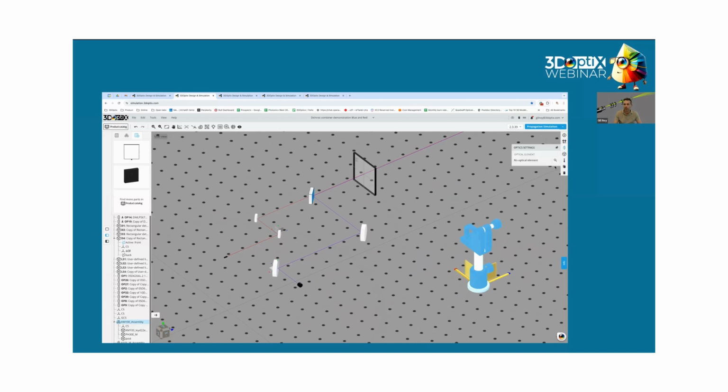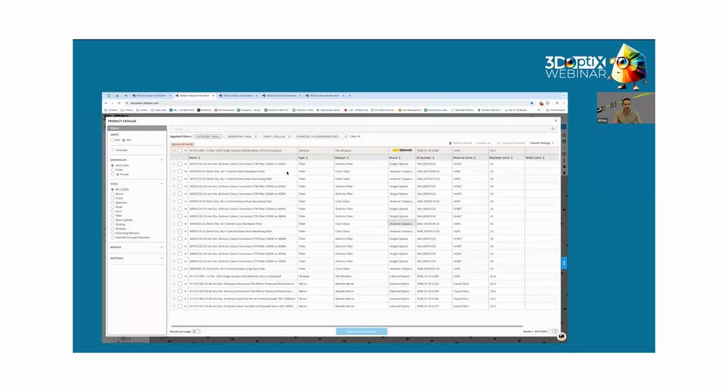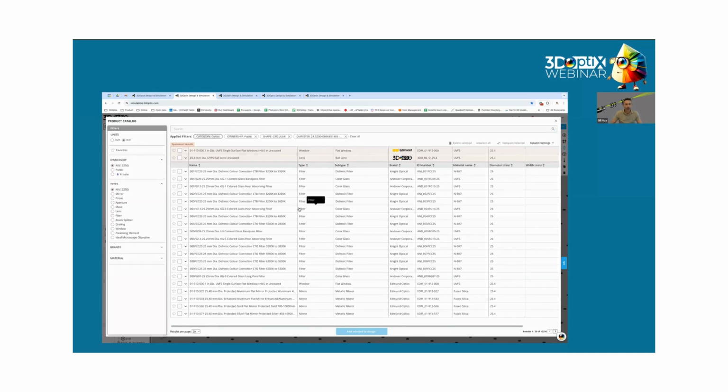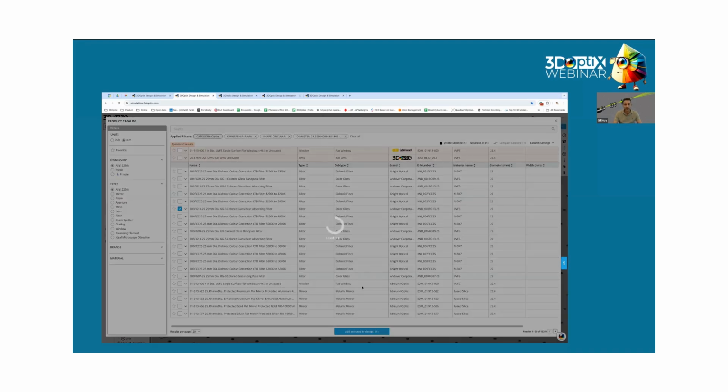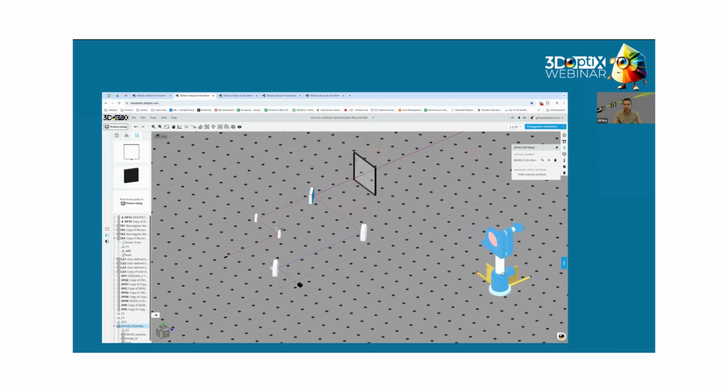And then you have an optical icon here. And when you press it, now the optical catalog opens with a filter that fits the size and the shape of that element. So it's circle 1 inch, so you can see fewer elements. And if you select one, automatically it would be inserted and they would be grouped, so you can work with it like this.